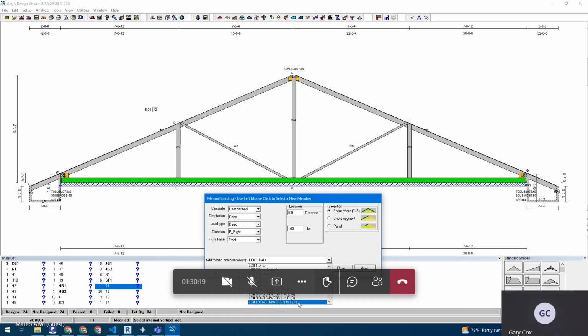All right. Now to add to load combinations, what happens is you can say all load combos, or if you were doing some kind of snow or wind, you could say if the load type exists, only add it then. Or if it contains the load type. So these will be helpful when you get into some special things you got to load, especially cupolas, towers, things like that that are going to be on top of, or solar panel.